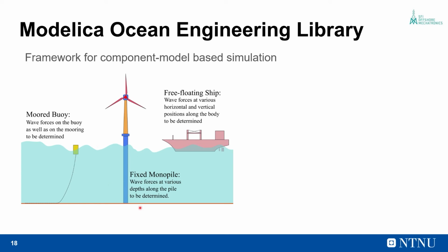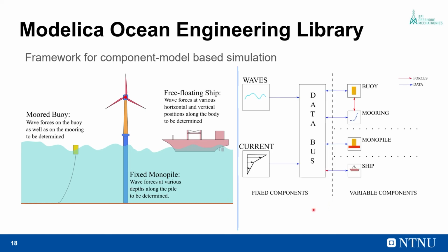Or maybe you want to calculate the wave forces at fixed structures like a monopile, or the structure could be free floating like a ship. So what is common in all these models is that the environmental parameters are common, but you need to calculate the loads only at specified locations.